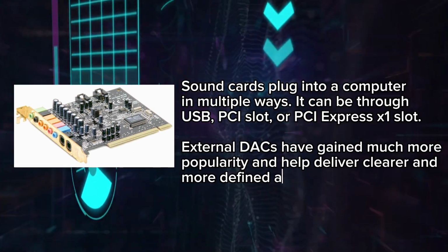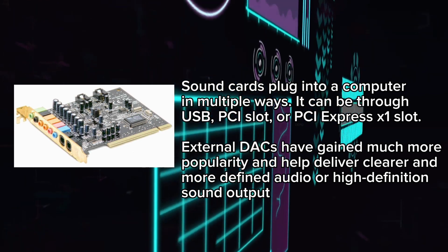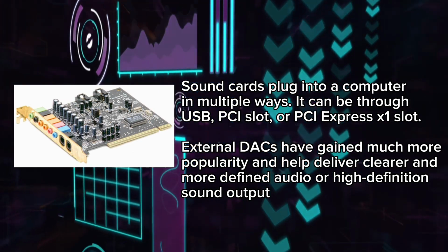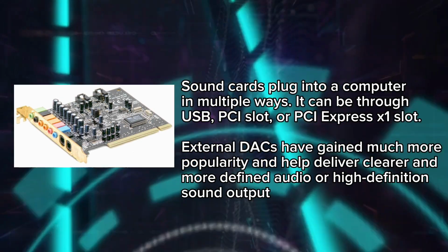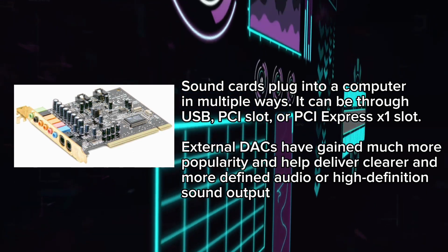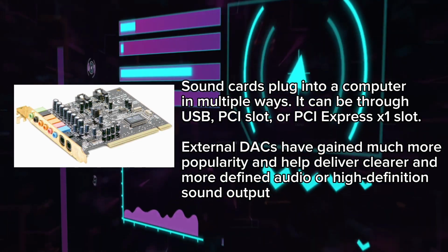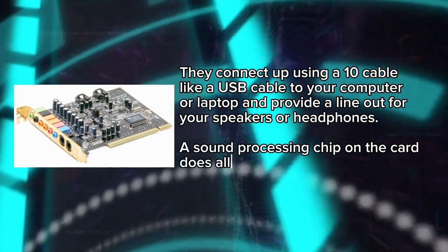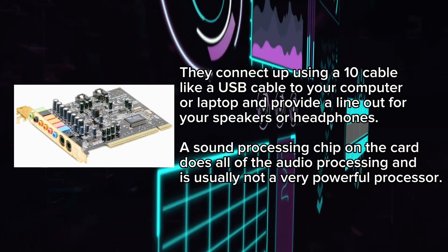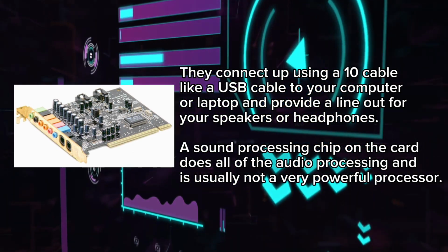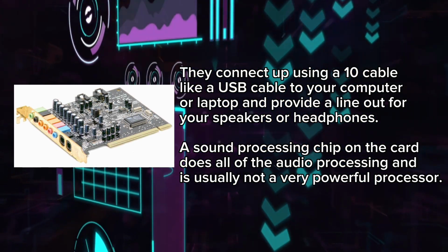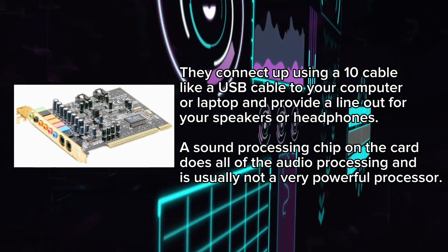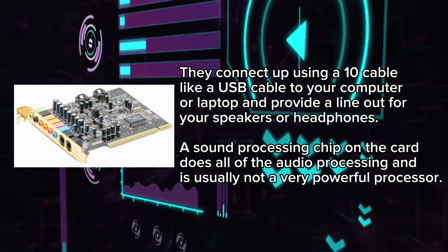Sound cards plug into a computer in multiple ways. It can be through USB, PCI slot, or PCI Express x1 slot. External DACs have gained much more popularity and help deliver clearer and more defined audio or high-definition sound output. They connect using a cable, like a USB cable, to your computer or laptop and provide a line out for your speakers or headphones. A sound processing chip on the card does all the audio processing and is usually not a very powerful processor.